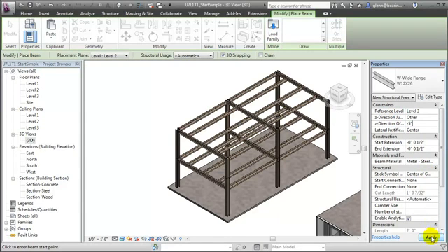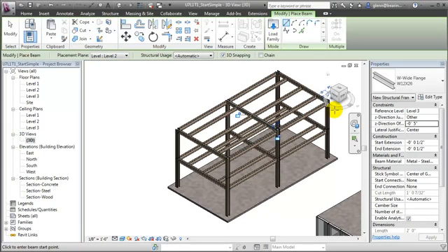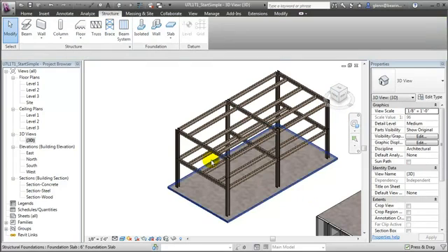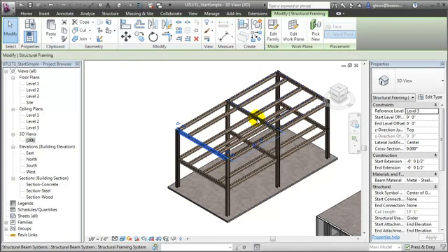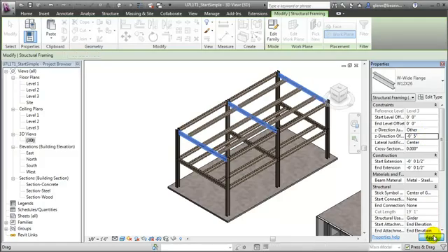We'll say Apply. Make sure that 3D snapping is turned on. Then place the new beam elements by snapping to the ends of the columns. And when the beam elements are placed, you'll see that they're actually placed 5 inches below the floor level. We can change the height of the existing beams too. To do that, let's select one, then Control-click to select the others, then choose the Z direction justification again, choosing Other, and let's make that also -5 inches. And Apply to lower those beams too.